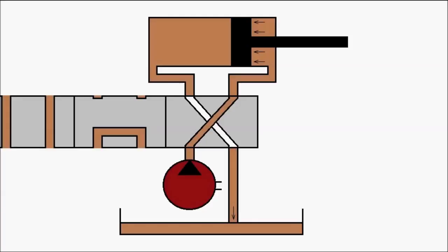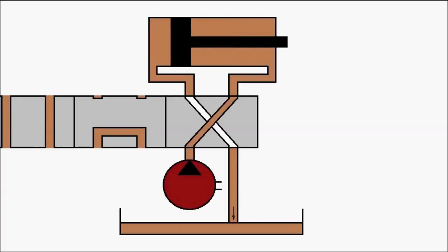It hits the piston at the rod side, pressurizes the piston at the rod side, resulting in the piston moving towards the head side. So oil from the head side goes back through the return line. You can see it's going back through the return line towards the reservoir. So this is how this particular circuit works, how the direction control valve controls the flow or redirects the flow towards the hydraulic ram, resulting in it working.